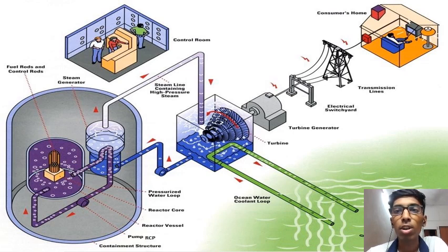This water is transported via the primary circuit to a heat exchanger, which is a steam generator that produces water steam. Secondly, this steam is transported to the generator turbine set via a secondary circuit. Once there, the vanes in the turbine move the alternator, and the alternator converts the mechanical energy into electricity. When the water steam goes through the turbine, it is sent to a condenser to cool off and become liquid water again. And then finally the water is transported to the steam generator to become steam again inside a closed circuit.